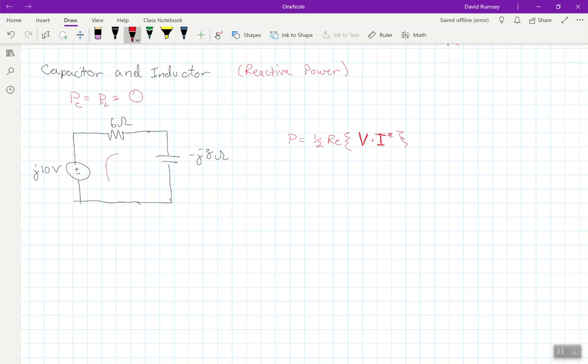What I'm going to do here is simply compute this phasor current I, because then I can use that phasor current to compute the phasor voltages of each of these terms and use that to compute the average power. So the phasor current, hopefully this is pretty obvious, because this is a simple series circuit. It's just going to be j10 divided by the sum of the impedances, 6 minus j8, which if we do this, I have this on my calculator right here, I did this computation.